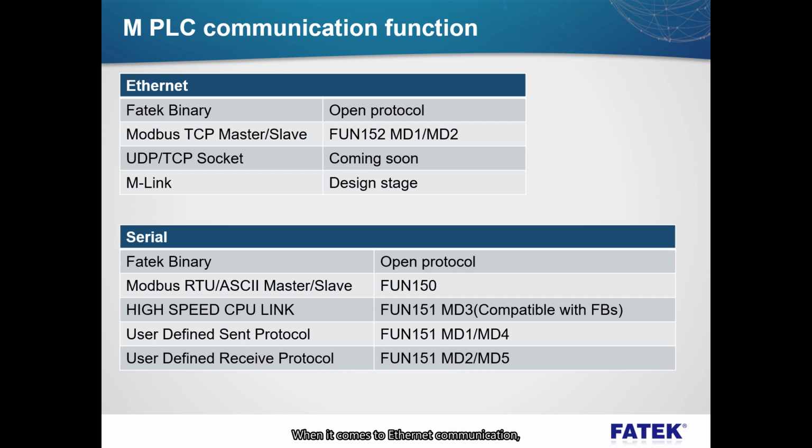When it comes to Ethernet communication, MPLC supports FATEK binary protocol, which will be open to the system integrators and alike. Modbus TCP master and slave are also supported by using function 152 for master and with proper configuration for slave inherently. Not only that, socket communication on UDP and TCP is coming soon, and the Ethernet version of CPU Link, M-Link, is also on the way but unfortunately still in design phase.